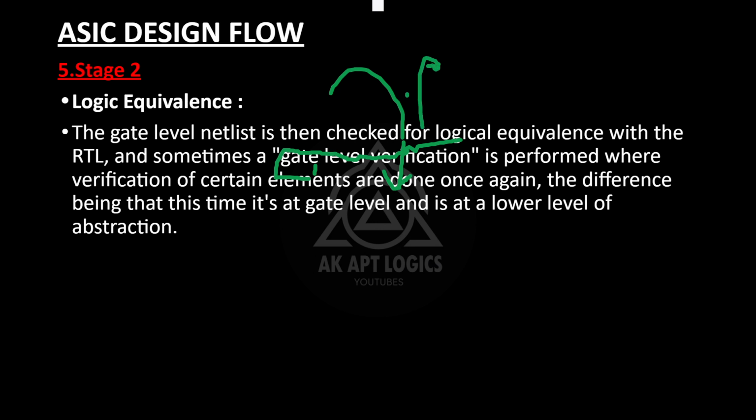So if you specify the design using only functionality, then the synthesis output hardware schematic will be very complex because you haven't mentioned any internal details of that particular module. The functionality will be achieved, but the circuit complexity will be more. Now we have to reduce that circuit complexity by converting into the gate level or the lower level of abstraction, in the sense RTL or gate level.